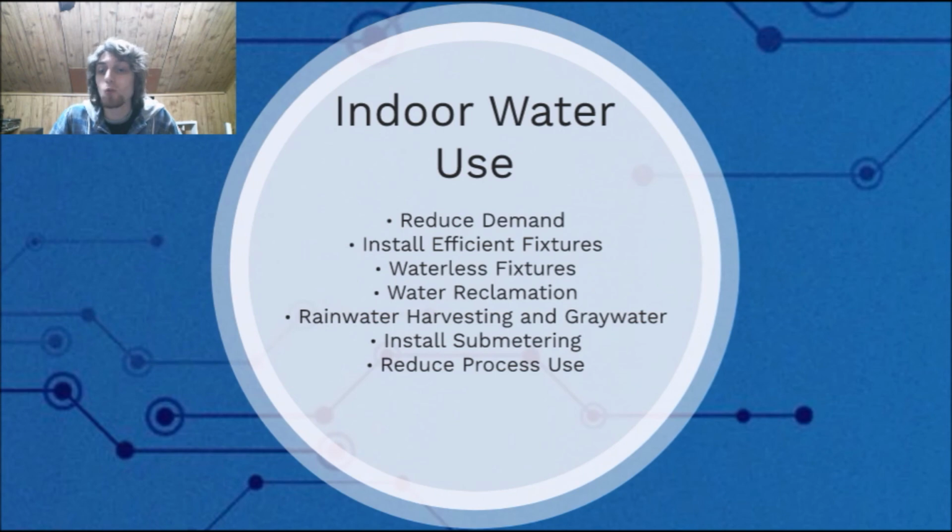We have ultra-low flow water closets as well as high-efficiency toilets that use a pressure tank for vacuum pressure. And this can reduce it to 1.28 gallons per flush, I should say. But then we have dual flush water closets, so it's mixed, a flush option for liquid and a flush option for solid waste. Ultra-low flow urinals. These can reduce flow to 0.125 using a pressure assist.